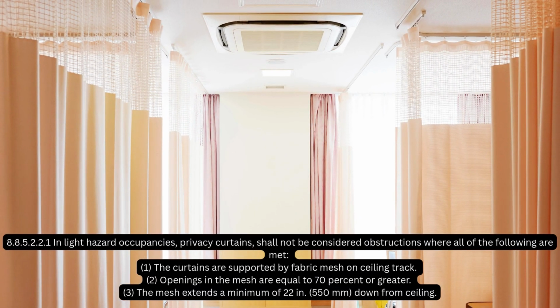8.8.5.2.2.1. In light hazard occupancies, privacy curtains shall not be considered obstructions where all of the following are met. 1. The curtains are supported by fabric mesh on ceiling track. 2. Openings in the mesh are equal to 70% or greater. 3. The mesh extends a minimum of 22 inches, 550 millimeters, down from ceiling.